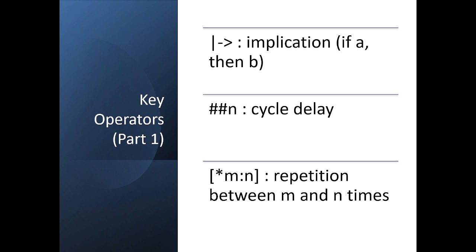These are some of the key operators available here, like the implication operator, cycle delay, and repetitions between m and n times. These are some of the foundations of SVA coding, and these are the things we use most of the time in SVA coding.